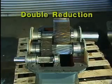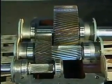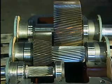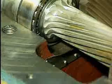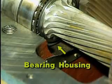This gearbox is a double reduction type. It steps down the motor speed in two stages. The first stage of speed reduction occurs across this helical pinion and gear. The second stage of reduction occurs across this pinion and gear. The pinions and gears are mounted on shafts, which are supported by bearings on either end. The bearings are supported in parts of the casing referred to as the bearing housings.